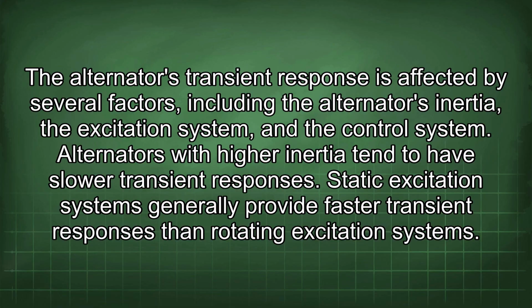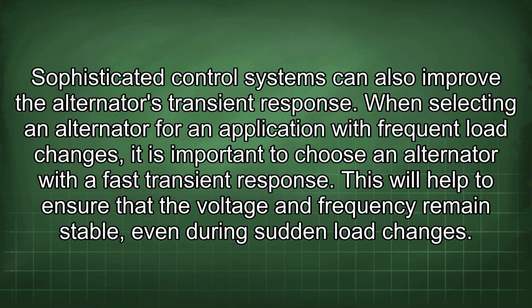Alternators with higher inertia tend to have slower transient responses. Static excitation systems generally provide faster transient responses than rotating excitation systems. Sophisticated control systems can also improve the alternator's transient response. When selecting an alternator for an application with frequent load changes, it is important to choose an alternator with a fast transient response. This will help to ensure that the voltage and frequency remain stable even during sudden load changes.